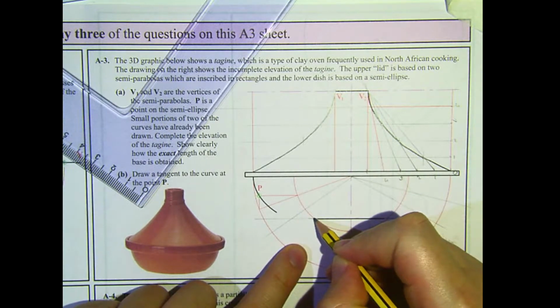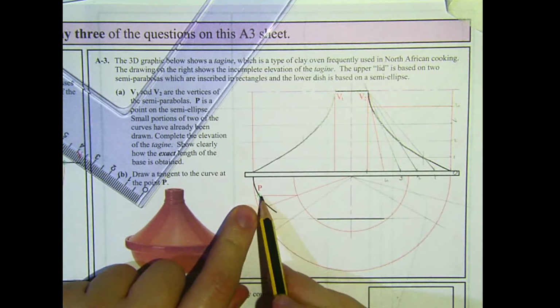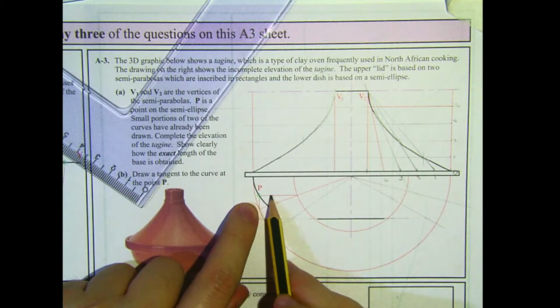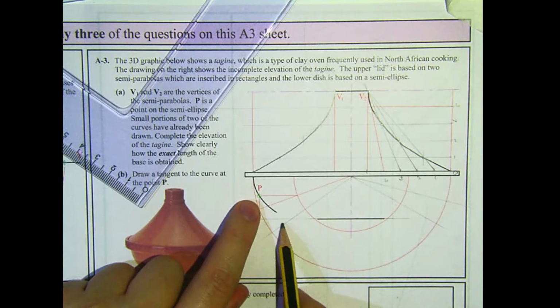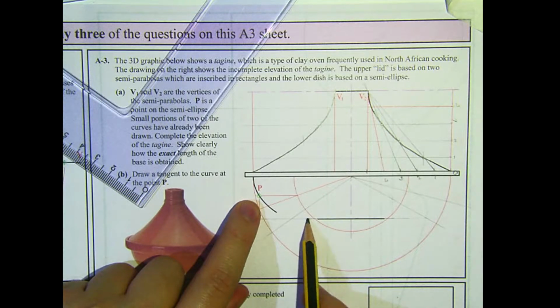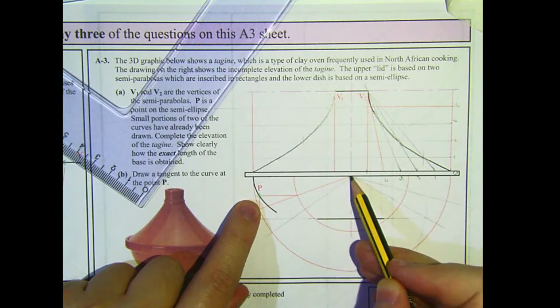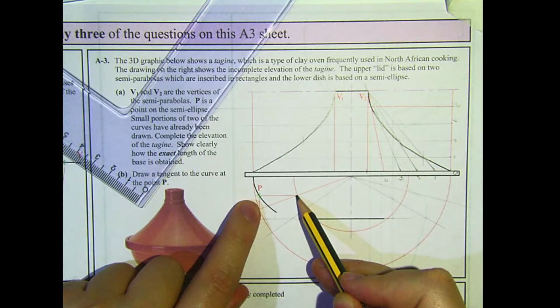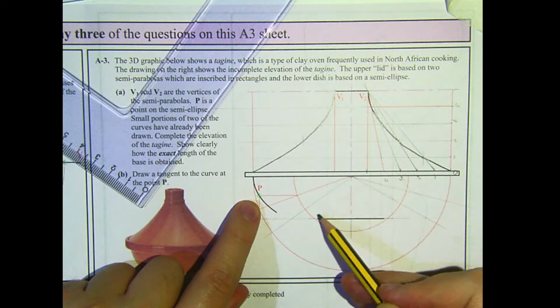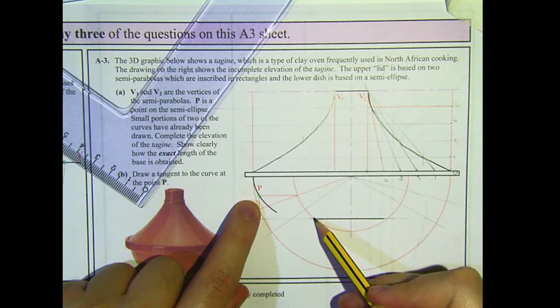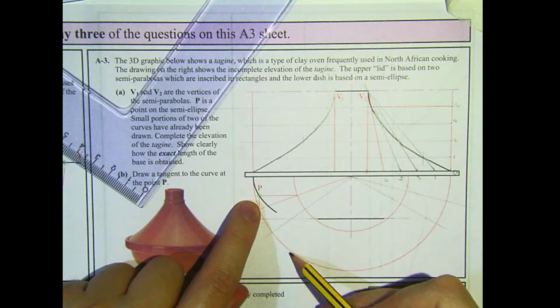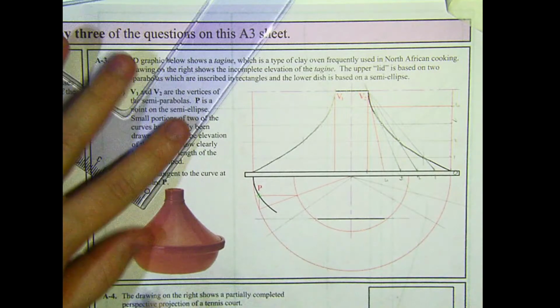So if we look at this here, point P is a point on the curve, we've got a horizontal line coming out of it. That's the equivalent to this line here. So we've got a line coming from the center that goes through this point. So what we're going to do is take a line from the center here that's going to go through where that horizontal line cuts the minor auxiliary circle, and then that'll come horizontal and it'll keep going on and we'll come up and that'll find the point that we're looking for there.